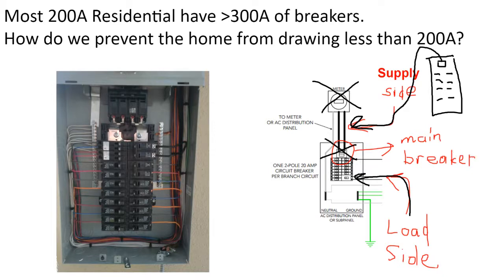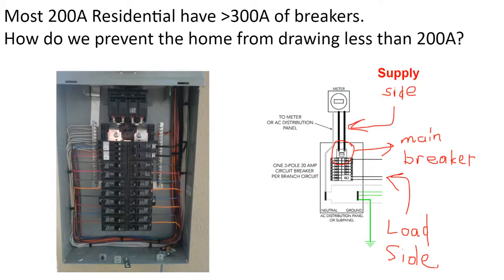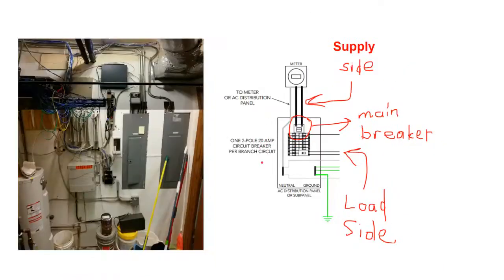But even for small interconnections, supply-side connections can be made. Sometimes the inside of the building's electrical system, quite frankly, can be a mess. A supply-side connection made outside the building, where the electricity leaves the meter and enters the building, can keep the system inspection outside the building.